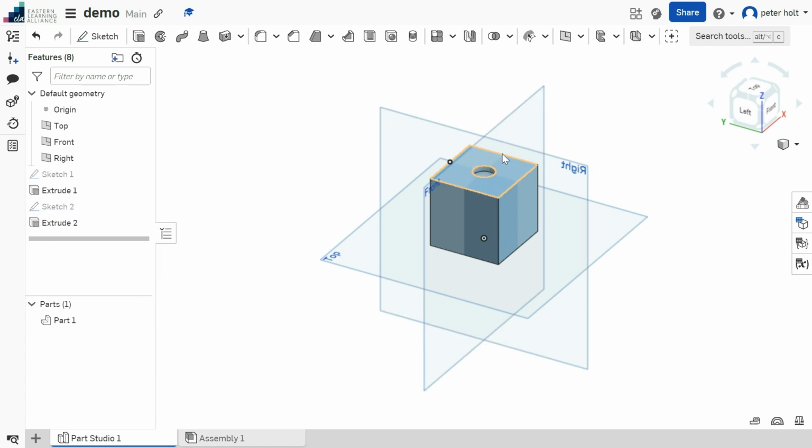When it finishes it off, it makes it into part of the shape, and it gets rid of the guidelines and the arrows. You can see now that I've got 2 sketches, both of them shaded out, and 2 extrusions. And if I ever want to get rid of anything, I can click on it, simply press the delete button, not the backspace arrow, but the delete button on your keyboard. It says delete on it. And then you will be able to have a second go at it. So you can go back into the sketch, edit it if you want, and then have another go at extruding it. So if ever these turn red, it means it can't do it.